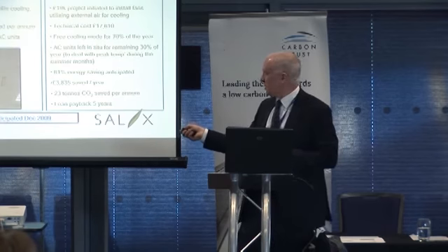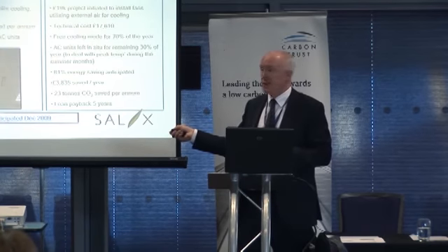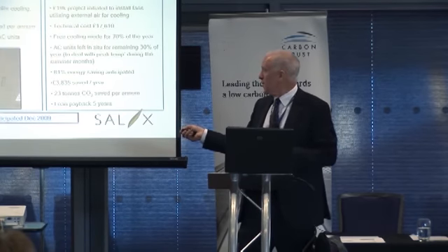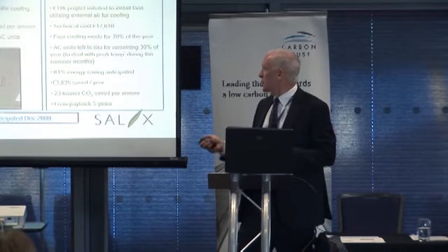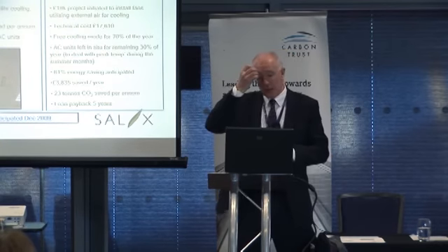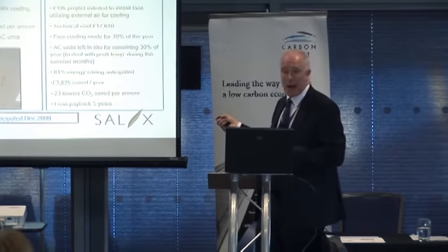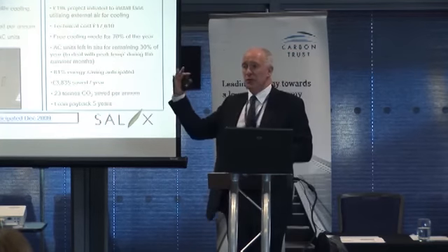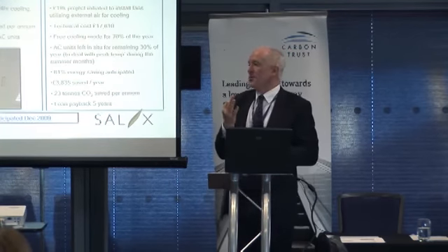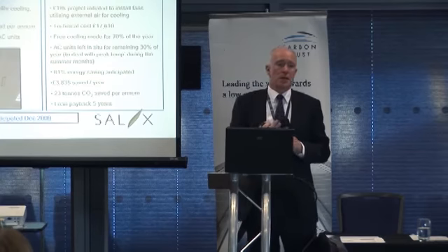Traditional direct expansion cassettes in the ceilings. And what they've done here is they've brought a simple fresh air input to replace these. The project cost less than 20k to do. And this now operates by bringing in filtered fresh air through their computer rooms. And that works for 70% of the year.